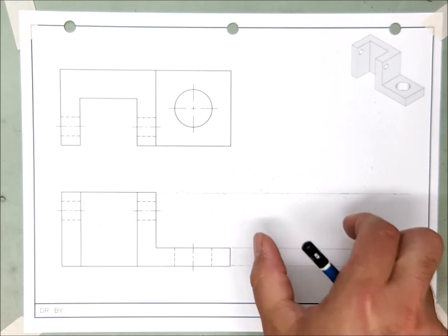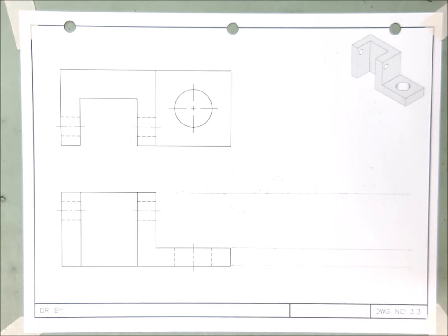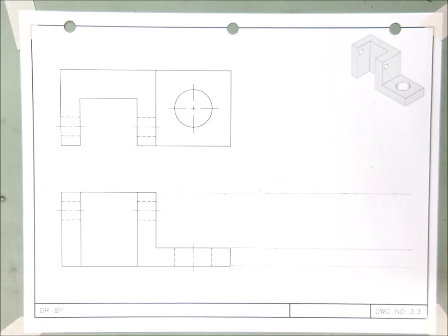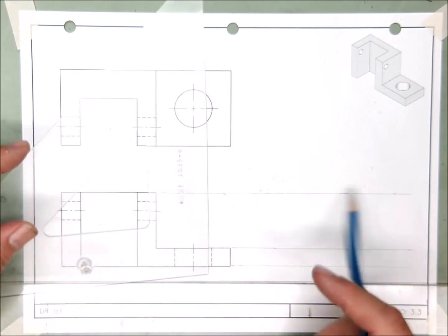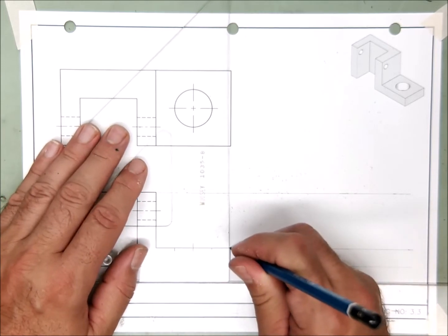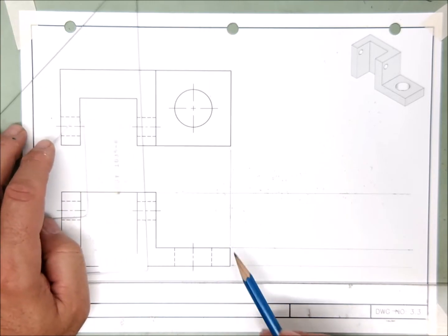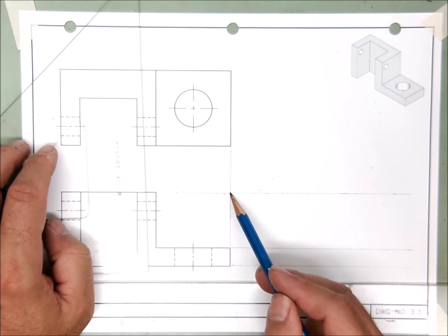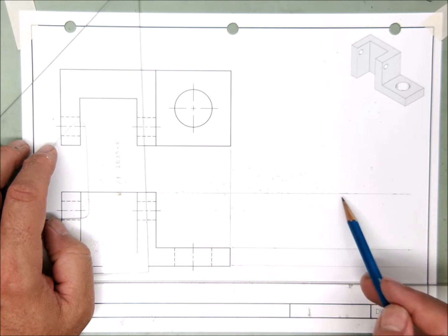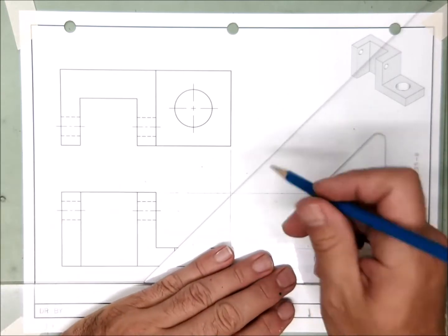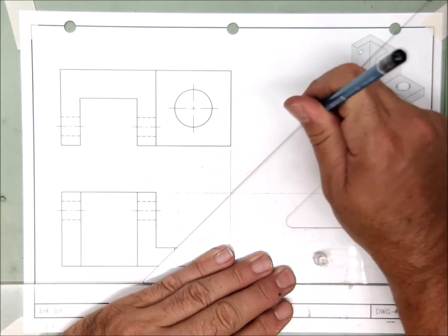Now I also want to get the depth over here, and we've discussed how every time we measure, taking a measurement and then transferring the measurement might not be the best way to do it, because there's always the chance when we measure we're going to blow it. So to avoid having that problem, set up a line at the far right edge of your front view, and then find this point, right? Find the intersection of the top of the front view and the right side of the front view, and from that point shoot a 45-degree line.